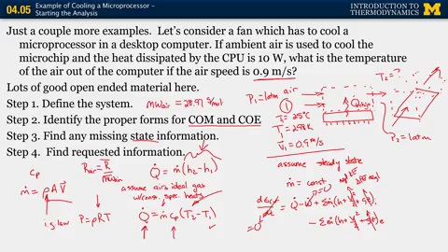You need to go find an appropriate form of the units for the universal gas constant and chug through that units conversion, plug in the appropriate pressure and temperature at the entrance state to get the density. And then if you're really feeling gung-ho, I want you to make an approximation about the flow area that would be appropriate for a CPU device, and evaluate the mass flow rate for the system.